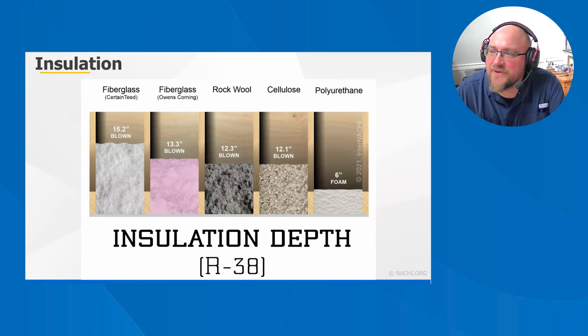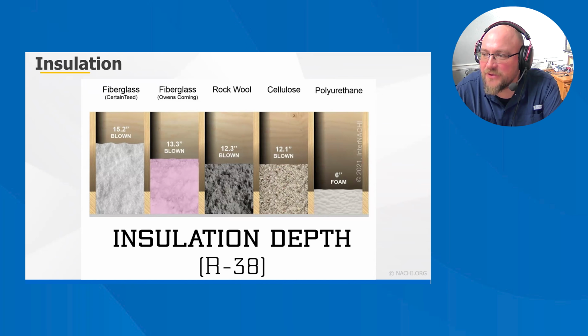Insulation provides resistance to heat flow. The more heat flow resistance the insulation provides, the lower the heating and cooling costs. Heat flows naturally from a warmer space to a cooler space. In the cold winter, this heat flow moves directly from all heated living spaces to adjacent unheated spaces such as attics, garages, basements, underfloor crawl spaces, and even to the outdoors. Heat flow can also move indirectly through interior ceilings, walls, and floors wherever there is a difference in temperature.